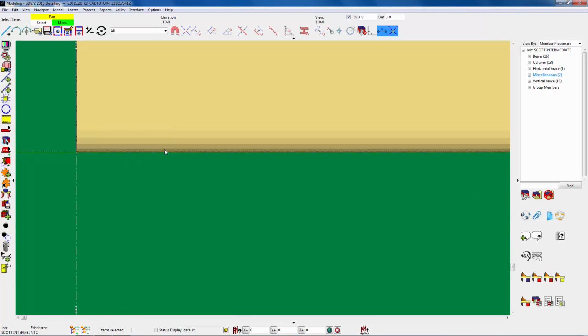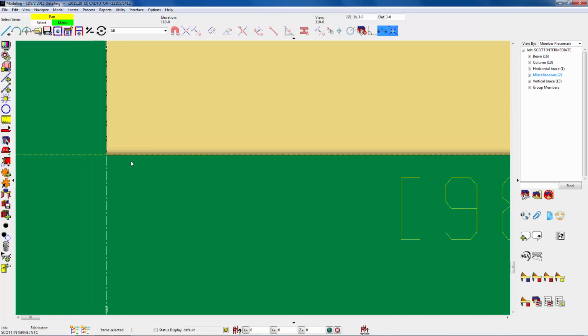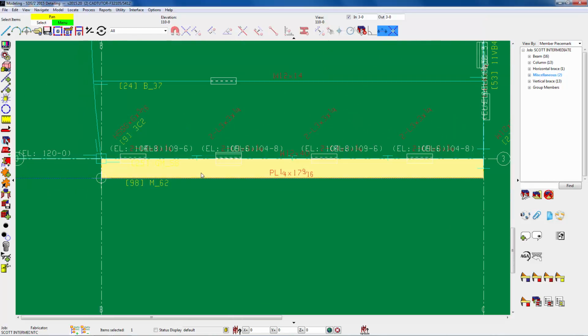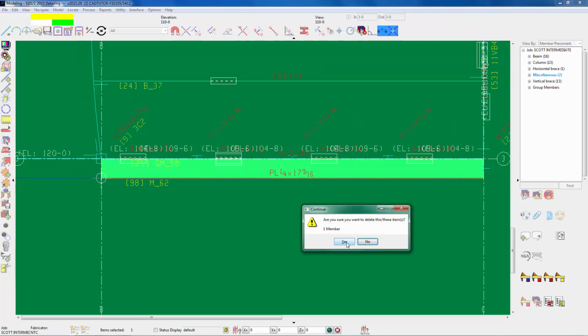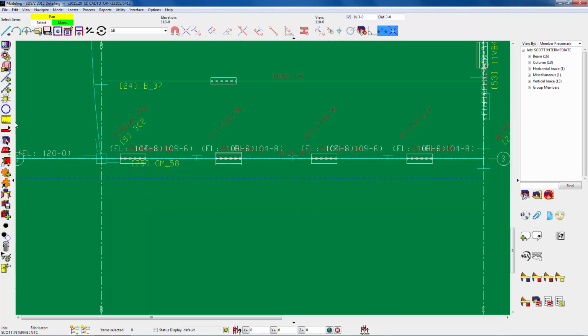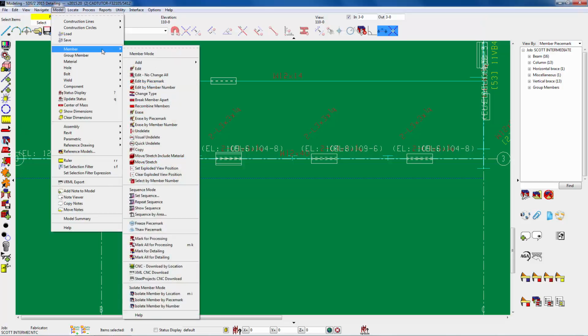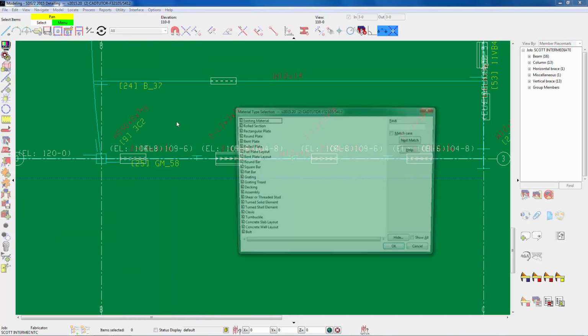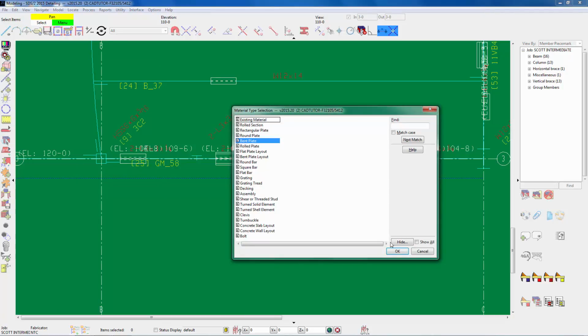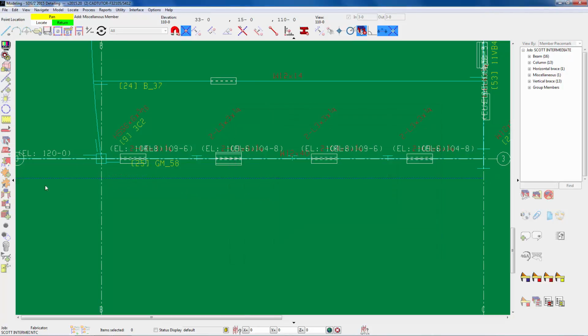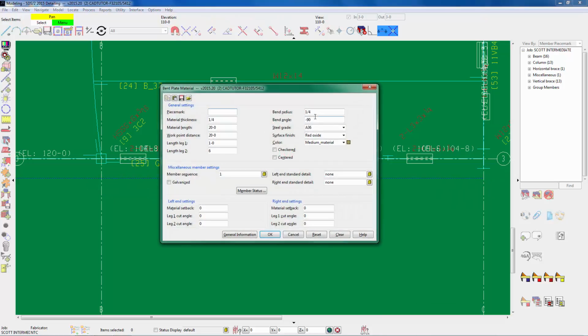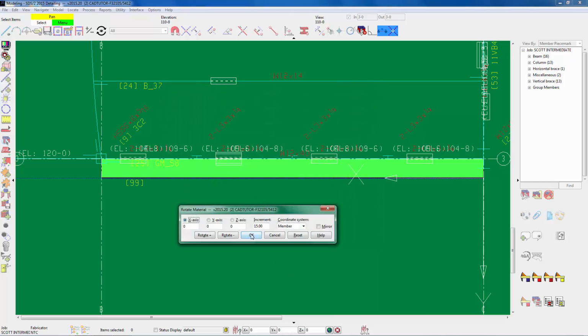But you can see my other leg, you can see that the bend here is down, so it's incorrect. So I'm going to take that back out, delete that back out there. Show you 2 different options here to put that member in. If I pick the same 2 points here from left to right, I could change my bend radius from negative 90 to 90, or if I pick from right to left and leave that negative 90, and I'm going to hit OK here.